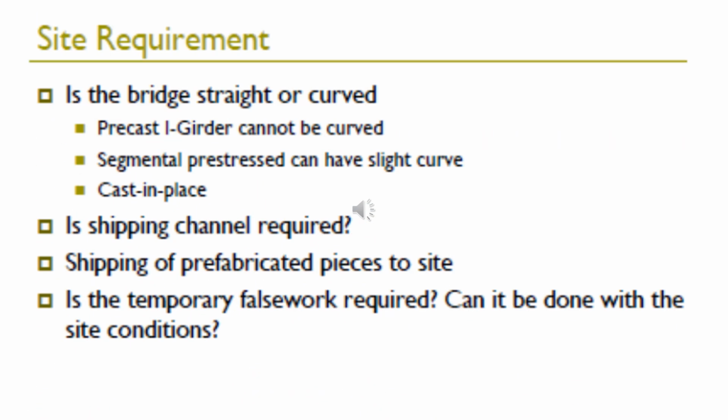Talking about the site requirement. First question, is the bridge straight or curved? Of course, we have to consider the following. Precast girder cannot be curved. Segmental prestress can have slight curve or cast in place.